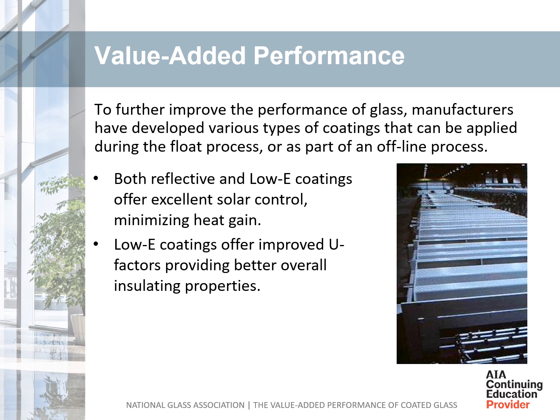Glass properties are altered with the addition of a coating. Generally, this can be thought of in terms of adding value to the glass product in some way. Coatings are designed and manufactured to impart a change to the performance of standard float glass types, and are generally manufactured by two processes: the pyrolytic process on a float line, or the sputtered process offline in a large area vacuum coater. Two important products are reflective and low E glass.